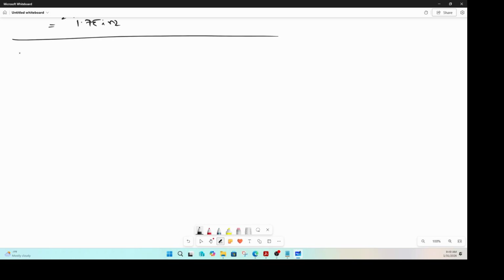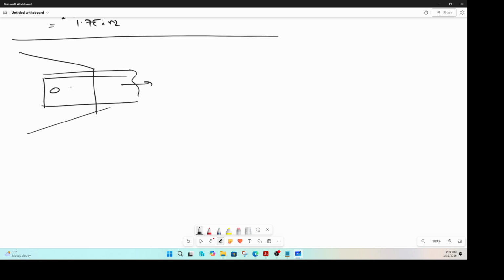Again, you have a gusset plate, you have something like that, and this time we have an angle. This is the tension member, and you have 3 bolt holes like that. Okay, this angle is an L 3.5 by 3.5 by 3/8 of an inch. That's the thickness of the angle. We have been given this information.